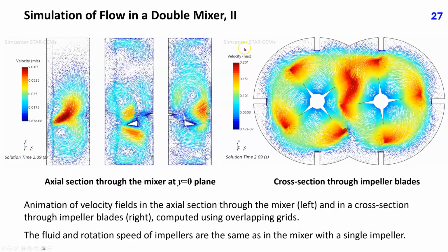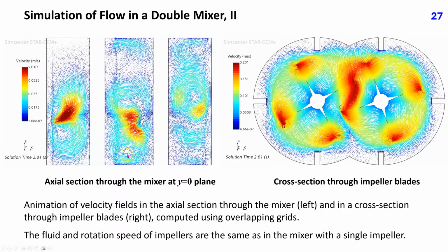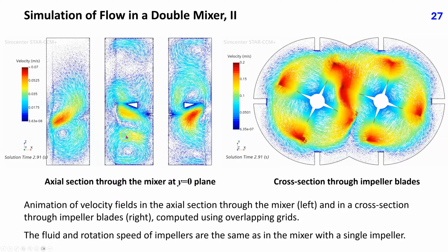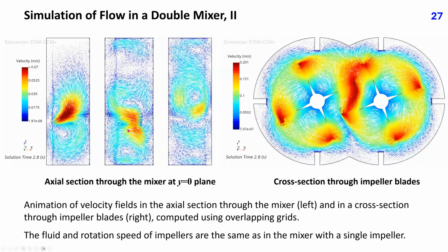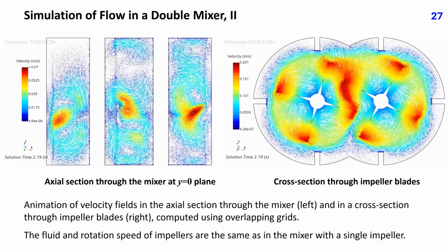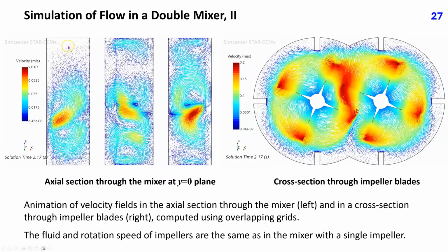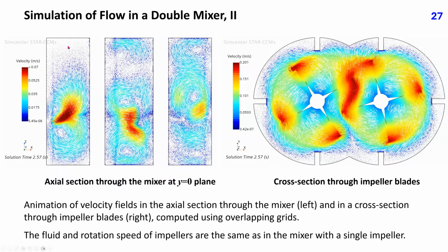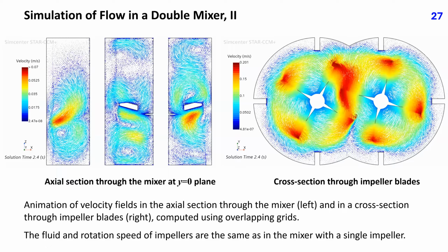In the vertical section, we see multiple vortexes, some of which are relatively steady, while the others are moving around, driven by impeller rotation. Plotted are velocity vector projections into the section planes. Small tangential vector components, like here, do not necessarily mean stagnant fluid. The velocity component normal to the section plane may be significant.